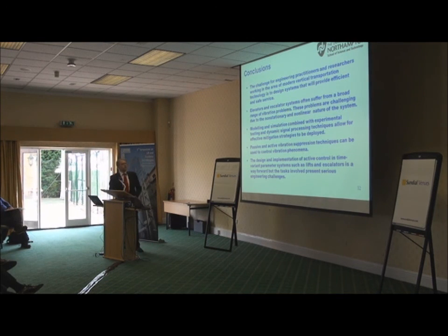Okay, so now as a brief conclusion, I have a couple of points to make. The challenge for engineering practitioners and researchers who work in the area of modern vertical transportation is to design a system which provides efficient and safe service. We know that both elevators and escalators suffer from vibrations, and the difficult part is that we have a complexity in the system. That means the tensions change, the masses change, the length of elements change, and this renders the system with time variant parameters.